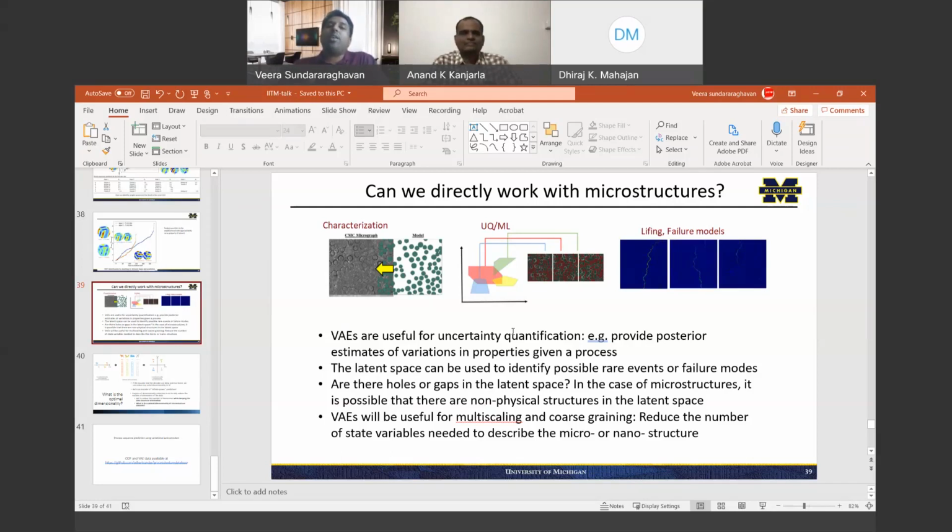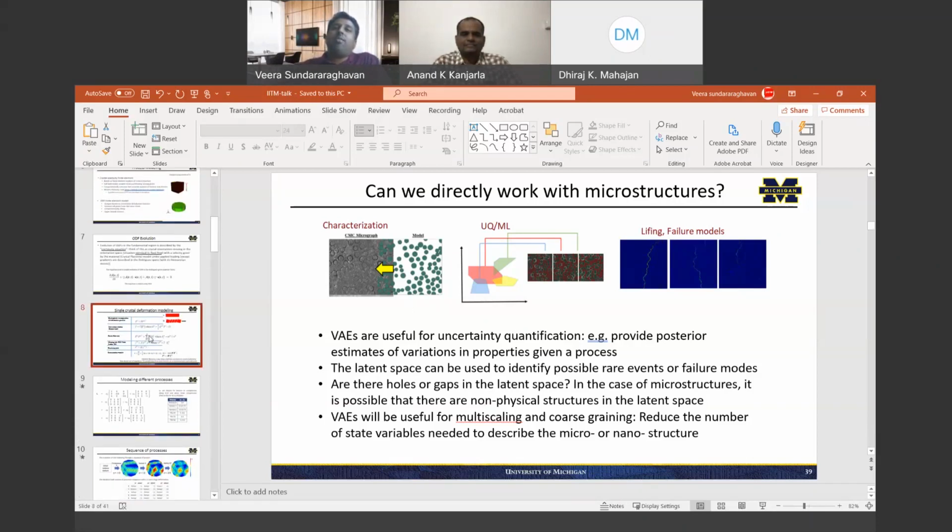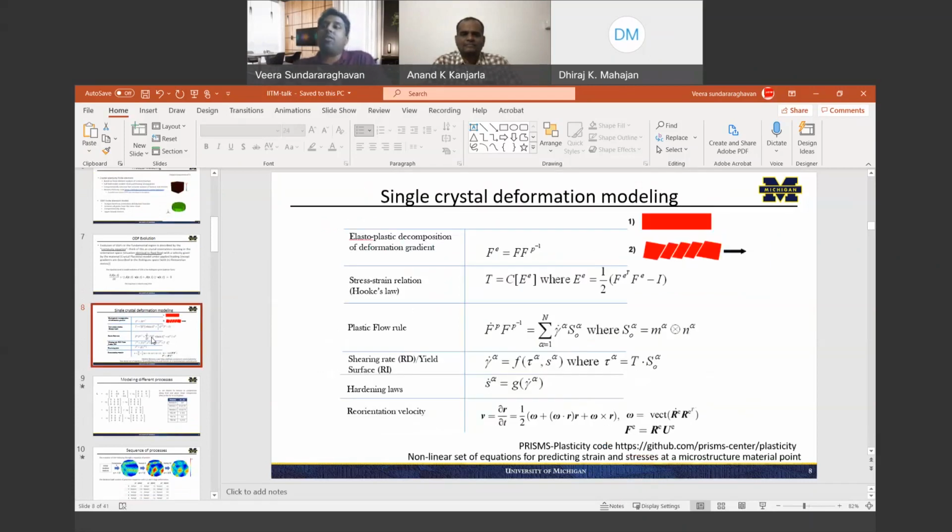The way the process model is generated, it uses this crystal plasticity approach, which takes care of the slip system resistances. So some slip systems may be hard so that you cannot deform them, or a system may not twin under tension, but twin under compression for HCP material. So you can put all that information in your computational model.